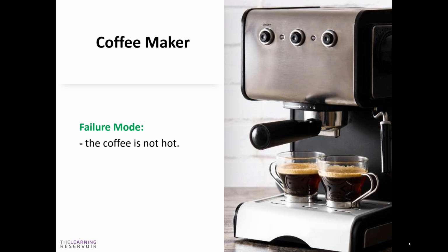Perhaps you're doing an FMEA at the design phase, so you do this brainstorming activity at that phase, or maybe you're doing a process FMEA. Maybe you're critiquing a process, a filling process, for example. What could go wrong during the filling process? You won't fill your bottles to the right volume. You might not fill them at all. So you list all, and they're all failure modes. What could go wrong? So that's a very important term, a failure mode in FMEA.